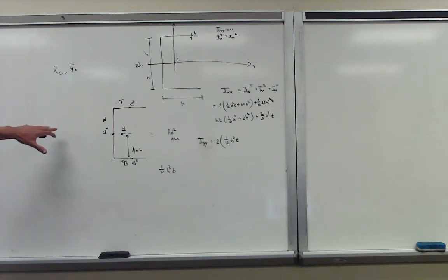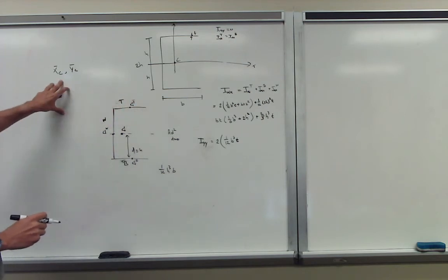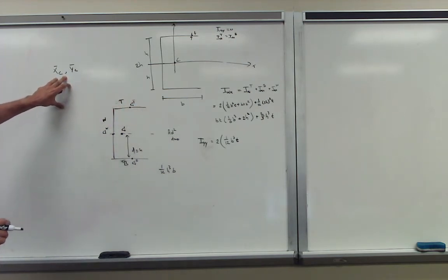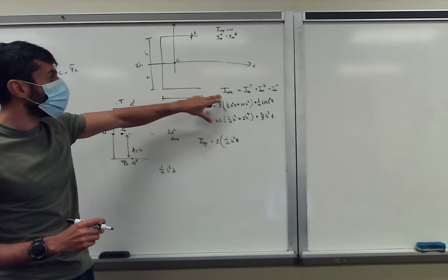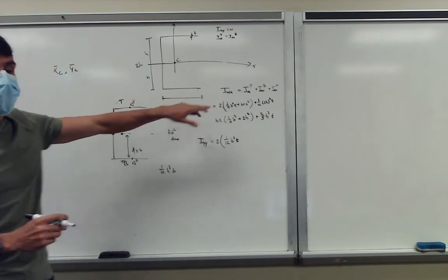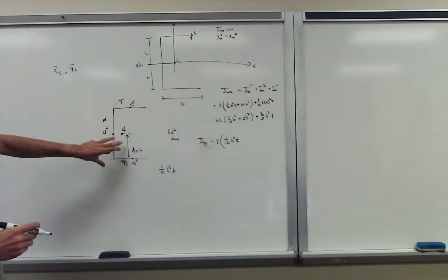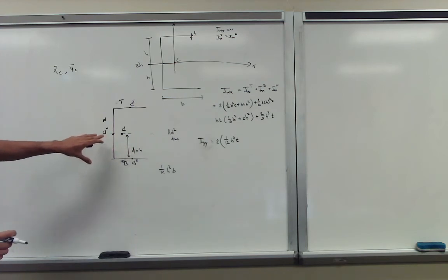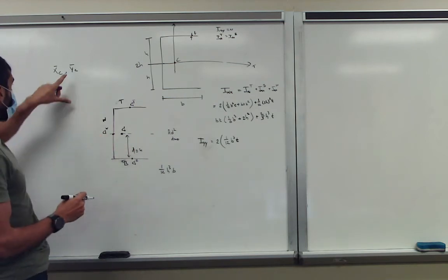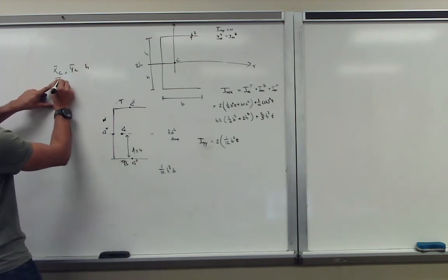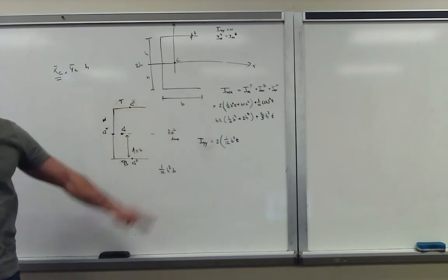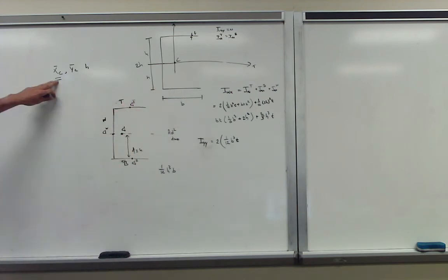So that's the first step actually, when the centroid is unknown. Depending on the problem, when the centroid is unknown, you often have to calculate the centroid location. Say, for example, if this is just a problem where you only have to use moment of inertia xx, then you don't have to calculate the centroid because you're not going to use it anyways, right? Because in this case, the y component is easy, that's h, but the x component is not something that you can easily get out of it. Let's call it cx for now.